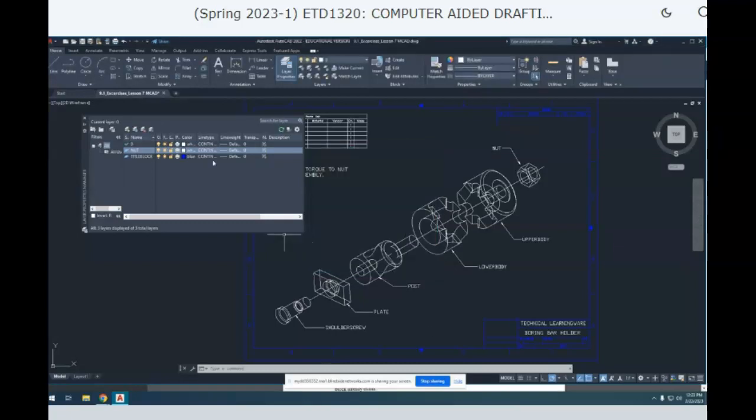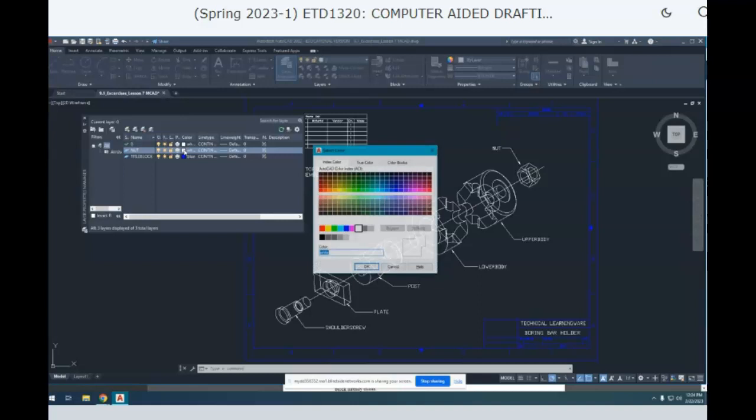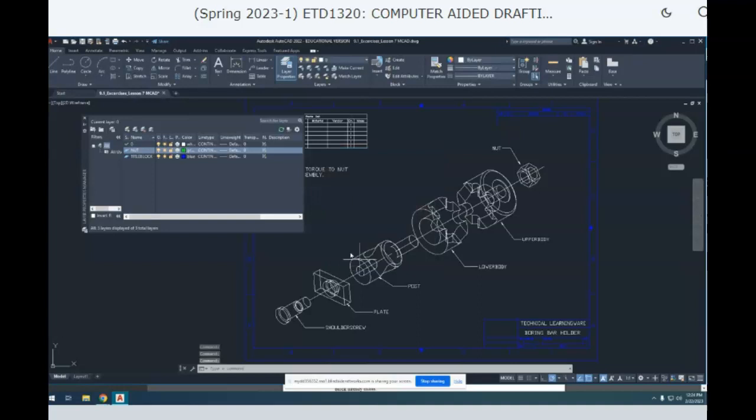So we're going to go in here and change green. How did you do that? First thing I did is I hit the star, I typed in the name, and now I'm going to change it to green. Click on that little box and choose green, say okay, and you will see it's on green. Now to make it current, you have to either double click on it to get that check mark, let me undo, or I can click the check mark here, select it and say check mark. When you make a layer active, it's the layer that you're using.